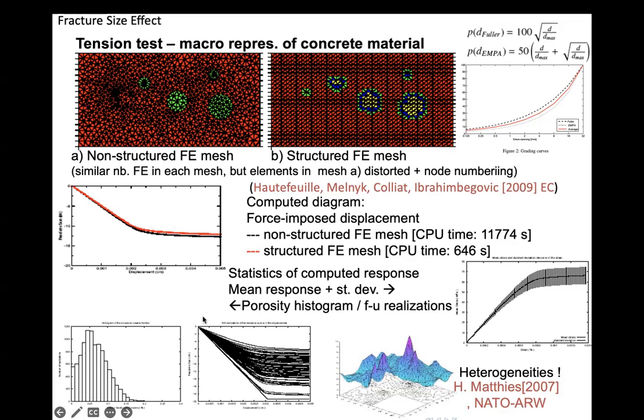and then you run the computation, assuming that the limit of elasticity will be when you have first plastification of the cement, modeled as elastic, perfectly plastic, and after that it spreads and has percolation. So ultimately we stop when you have a percolation, when plasticity goes from one end to another.